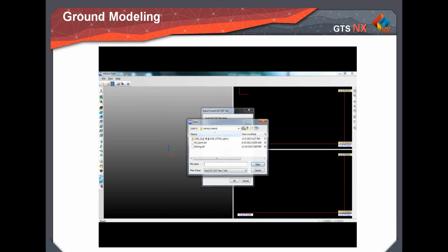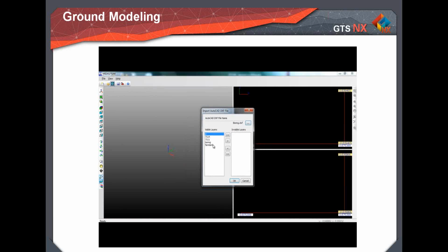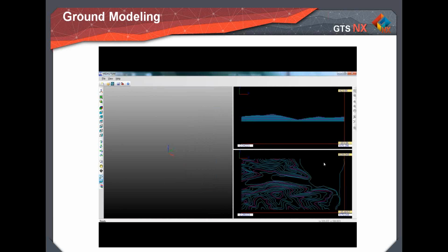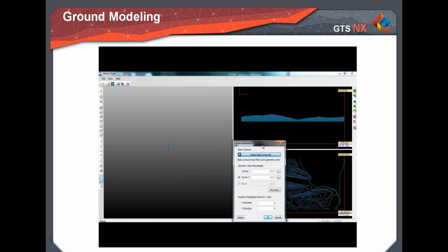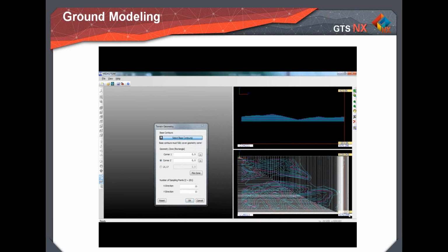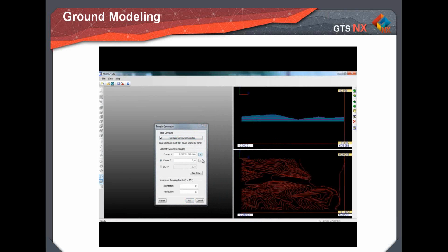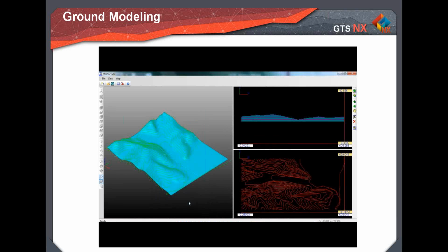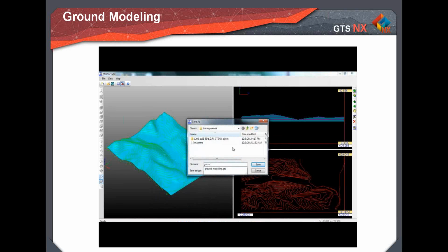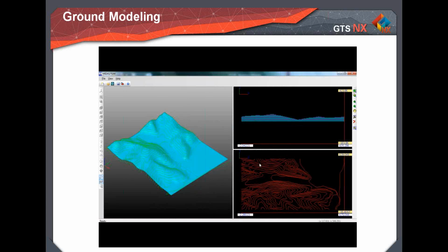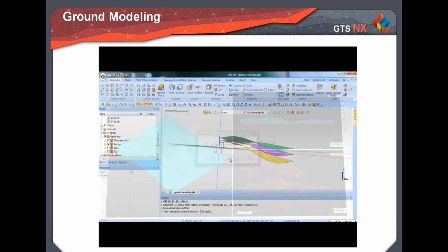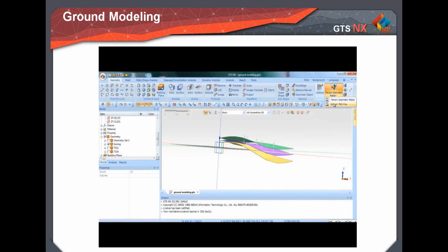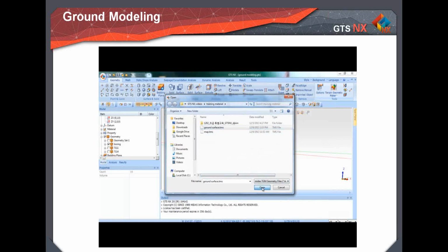And now that the soil strata has been defined, if you have a very detailed contour map available to you, you can open that, or you can import it, excuse me. And using the TGM feature, the Terrain Geometry Maker, you can take your various curves, as shown here, and use this 3D AutoCAD file to create a 3D surface that you'll later use to cut a solid and to make a detailed 3D model. So as you can see, here's the surface. You just have to save it under a separate file. Okay. And now you just have to import it into the program itself.